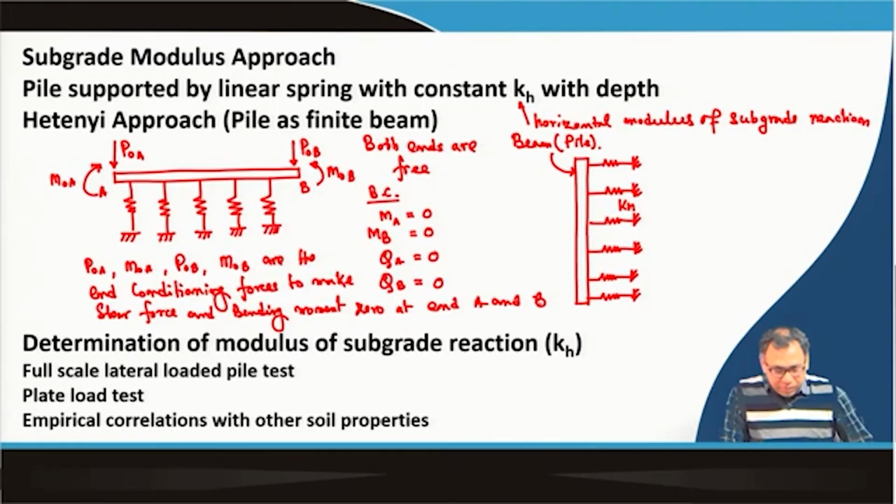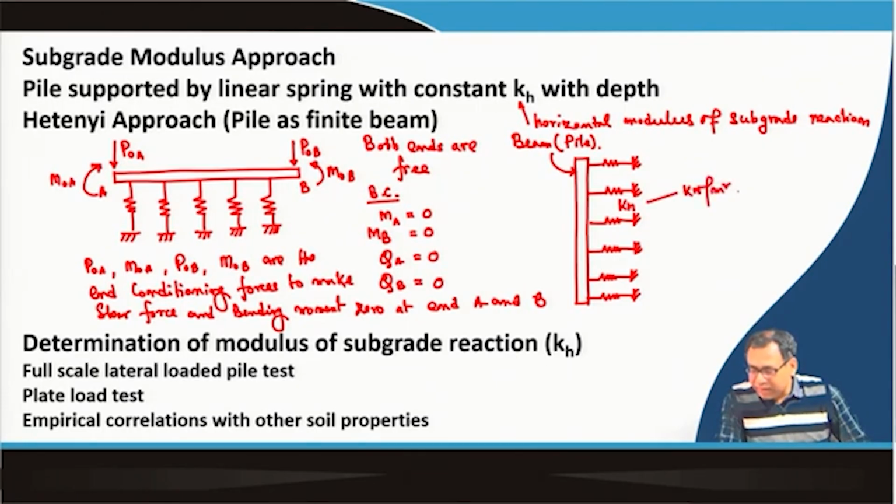So, now for the lateral loaded piles, what forces will act? We can suppose it is a free headed pile. So, first condition will be the free headed pile, then I will discuss the fixed headed pile. Before I go for that, how can we determine this kh, because I have already discussed how to determine the kv or the subgrade modulus. So, kh unit is kilonewton per meter square per meter.